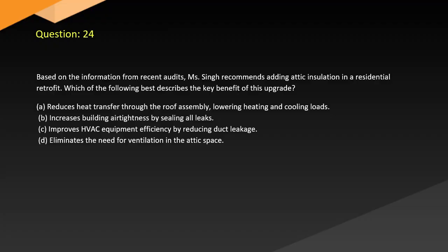Question 24. Based on the information from recent audits, Singh recommends adding attic insulation in a residential retrofit. Which of the following best describes the key benefit of this upgrade? A. Reduces heat transfer through the roof assembly, lowering heating and cooling loads. B. Increases building air tightness by sealing all leaks. C. Improves HVAC equipment efficiency by reducing duct leakage. D. Eliminates the need for ventilation in the attic space.